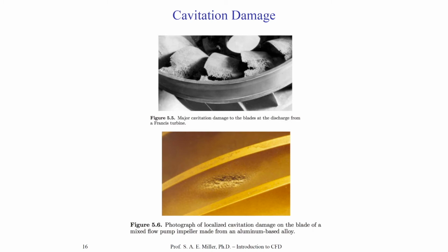You can see that eliminating cavitation through CFD studies might greatly prolong the lifespan of these types of liquid turbine systems. The lower photograph is the localized cavitation damage on a particular blade from a mixed flow pump impeller, and the propeller blades themselves, of course, are made of aluminum. So you can go in and see these microscopic or even large-scale effects over time from cavitation. You can imagine how ineffective these blades are while they're still running with effects of cavitation.